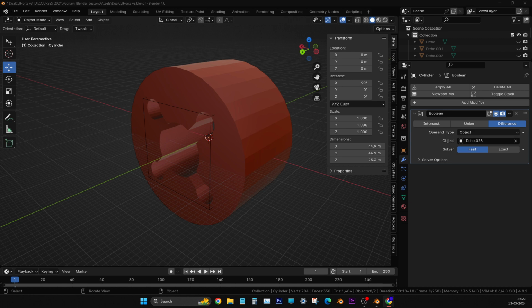Now, just press on that quadriflow remesh. It will show one dialog box. In that, let's switch on this mesh boundary, not sharpness, mesh boundary. And use mesh symmetry. Okay, let it be there.